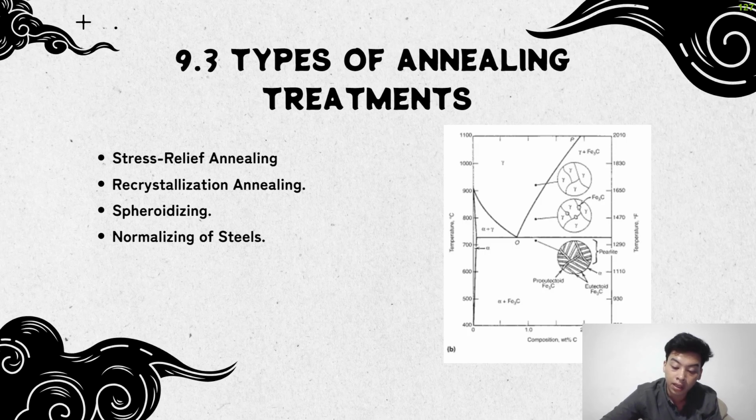Stress relief annealing. Annealing at subcritical temperatures below AC1 includes three different temperature regions. The first is the temperature range for stress relief annealing. Recrystallization annealing. When cold worked metals are heated to a sufficiently high temperature, the badly deformed cold worked grains are replaced by new strain-free grains.